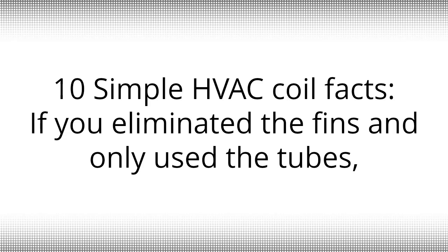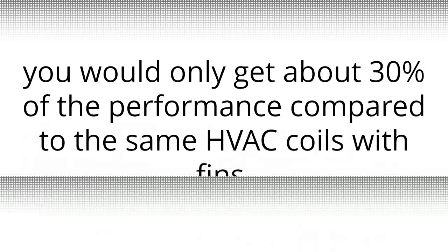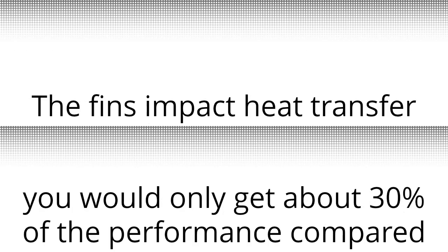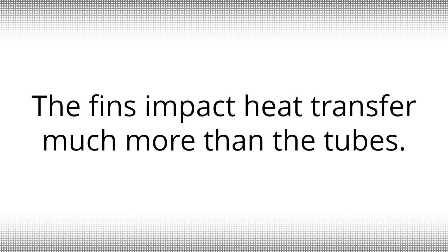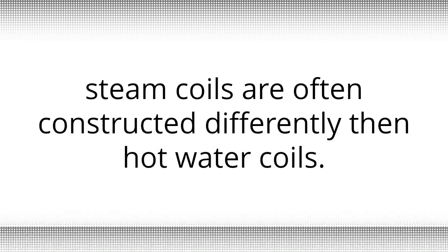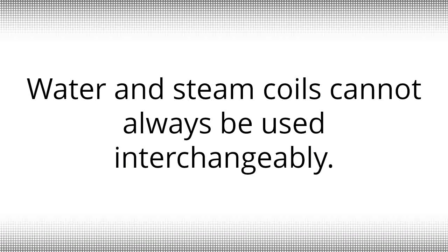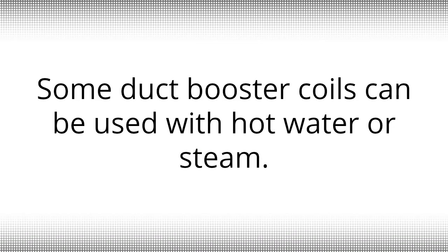If you eliminated the fins and only used the tubes, you would only get about 30% of the performance compared to the same HVAC coils with fins. The fins impact heat transfer much more than the tubes. Because steam is erosive, steam coils are often constructed differently than hot water coils. Water and steam coils cannot always be used interchangeably. Some duct booster coils can be used with hot water or steam.